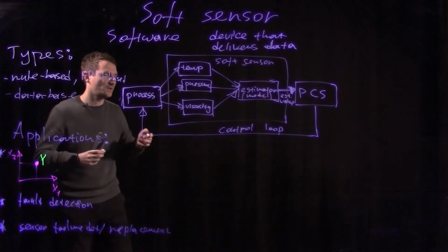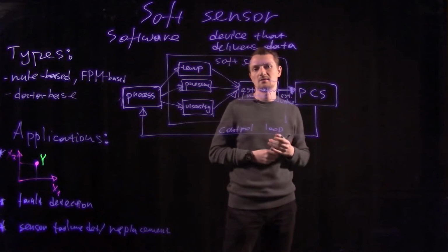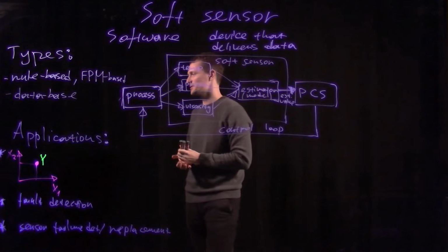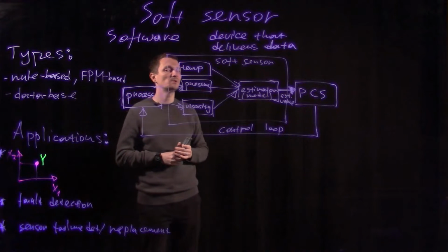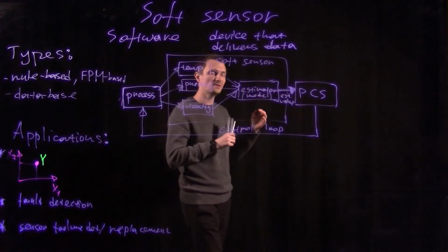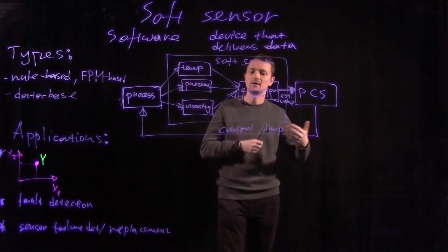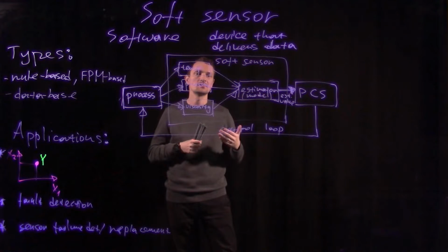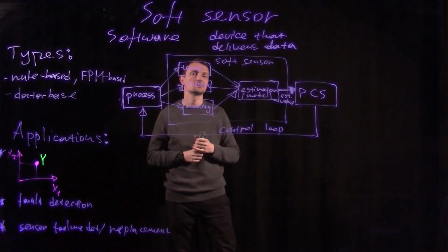For example, you can imagine you have a distillation column with maybe 10, 20 temperature sensors or pressure sensors, and one of them doesn't work anymore. In this case, you can remove it. You can first identify that your sensor, for example, returns every time zeros or the minimal value, although the other sensors are returning plausible values.